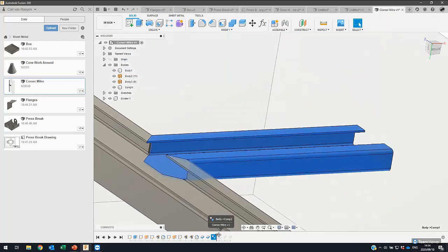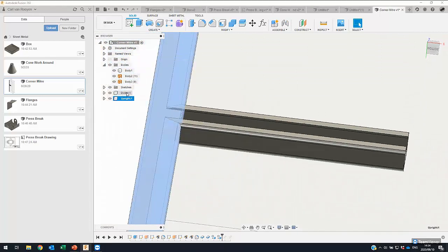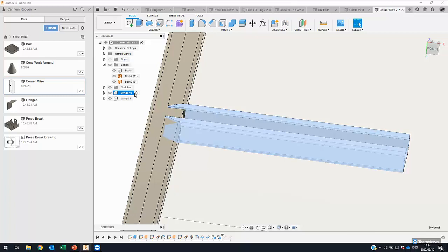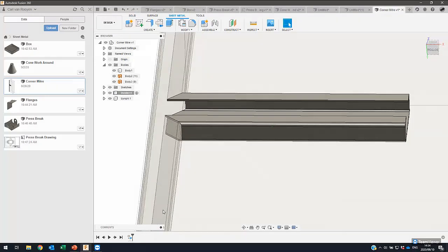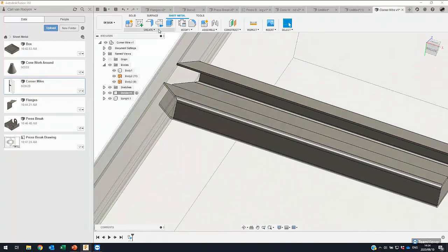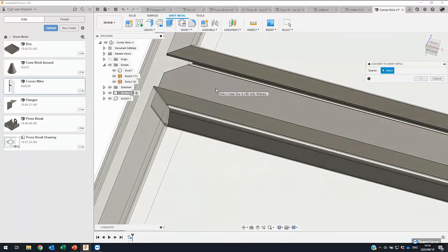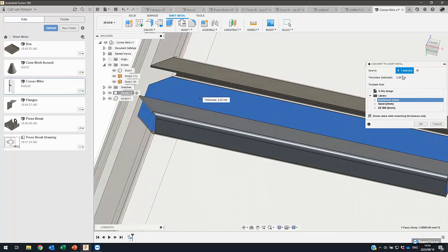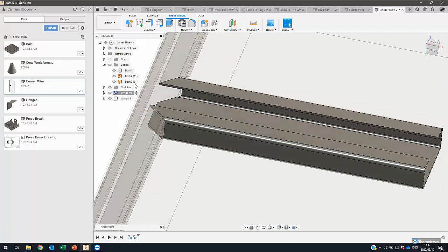It is now a component, and the second one is also converted, and each of those can then be activated, and we can then continue with any other processes. So in actual fact, if I go here and convert this, thickness detected 2 millimeters, I'm going to go stainless steel 304.